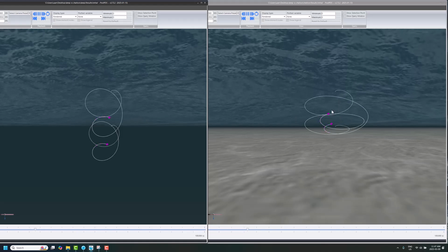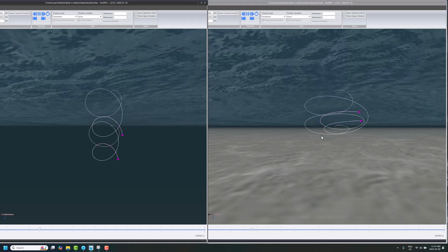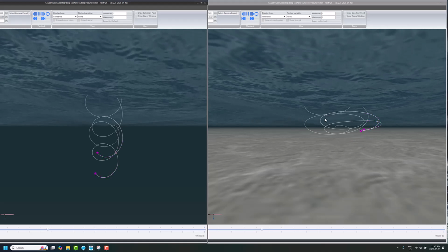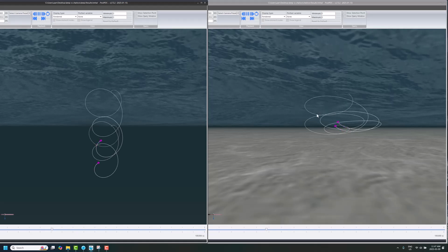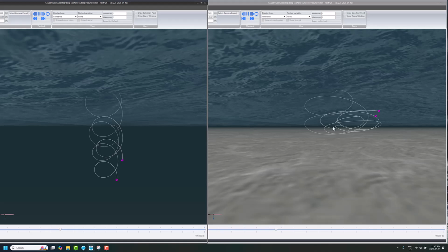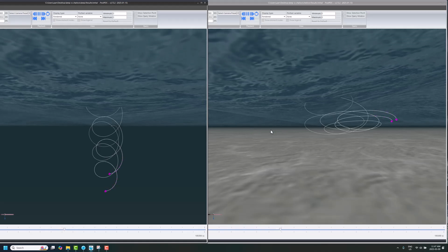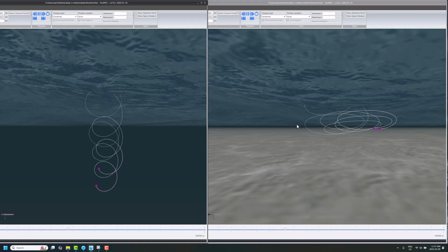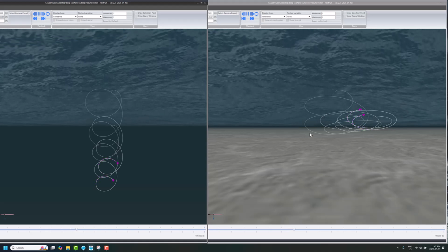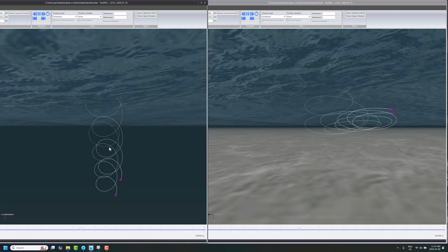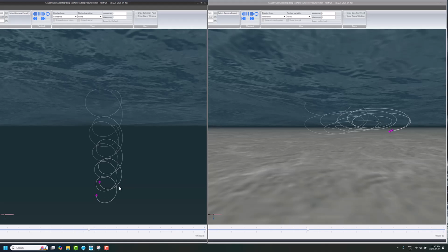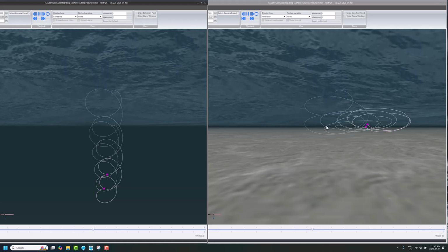Now, over on the shallow water case, the seabed really creates a compressing effect on the waves. It does affect the shape of the wave. Ultimately there is way more surging back and forth in the flow under the water surface from the water particle motions, and you get a much more elliptical pattern. You can see I haven't quite got things balanced perfectly; they're gradually sinking over here. But you see a much more circular trajectory in deep water and a much more elliptical trajectory in shallow water.